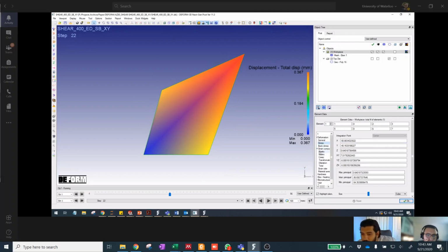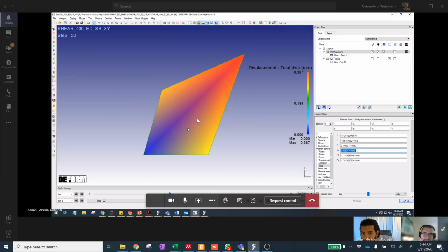And then you also have the strain components. None of these are active, so total component. Here, the thing is, for pure shear, these should be 0, right? Yeah. And the deformed shape that you have on the screen here doesn't look like pure shear though. That's the problem, exactly. That's the boundary condition here. That's my conflict, because I'm following this exact approach. I also ran a couple of other simulations with what pure shear is supposed to look like, and those are also not giving me the right answer. So I guess we can take a look at those.